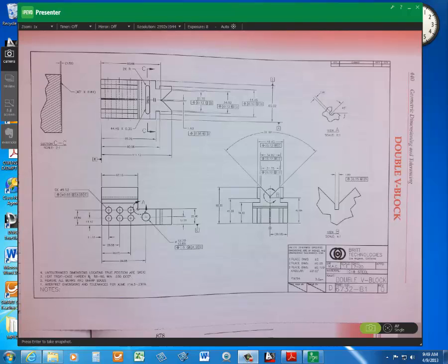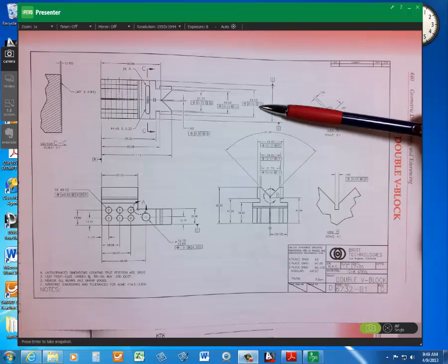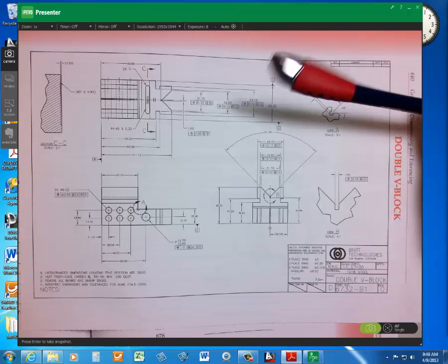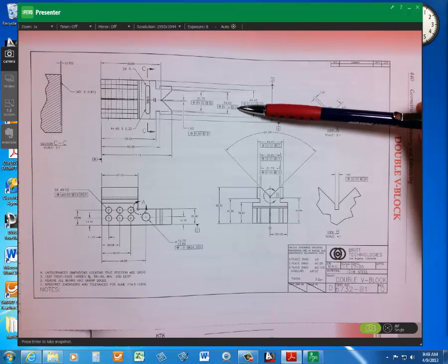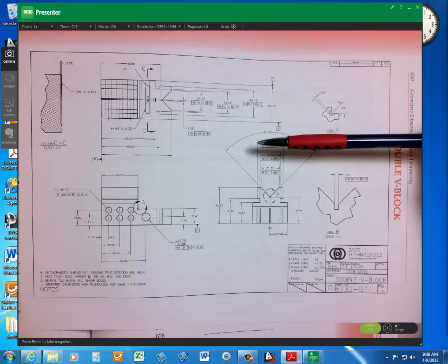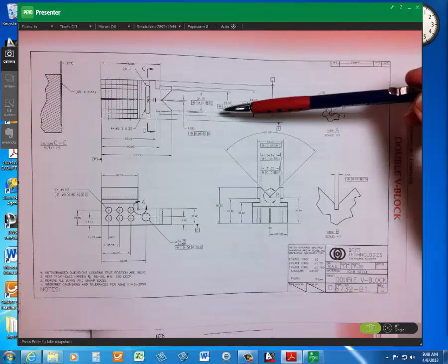Looking at the 44.45 dimension. Picking this thing apart up here. It's a 0.12 position tolerance zone. Okay, and references datum D, regardless of feature size. Oop, right here. All right, and the meaning of the information is basically reading it.